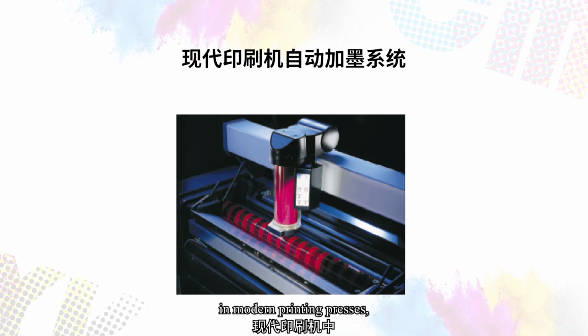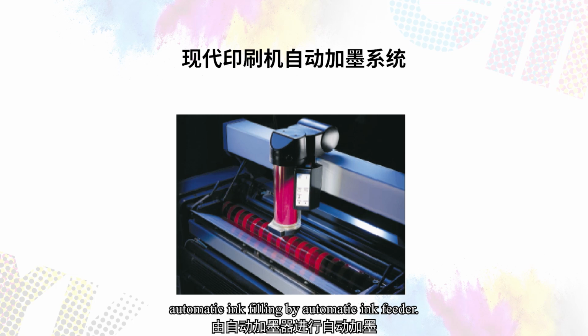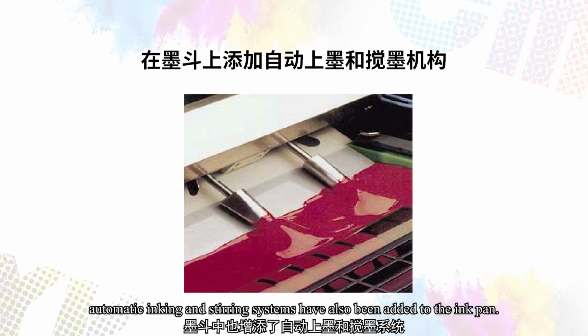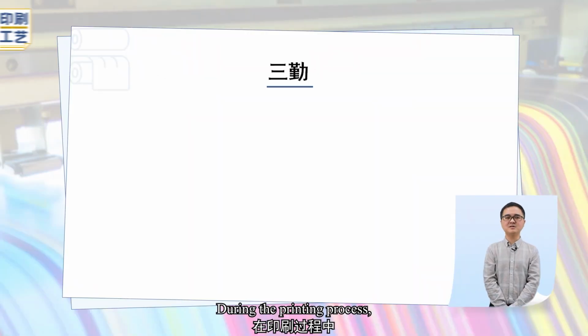In modern printing presses, an automatic inking system is often added. Sensors on printing equipment will monitor at all times. Once the ink level is reduced, the automatic ink feeder fills the ink automatically. Simultaneously, on many printing devices, automatic ink stirring systems have also been added to the ink pan. Once the fluidity of the ink in the ink bucket decreases, the automatic ink stirring system will work to ensure the fluidity of the ink during the printing process.